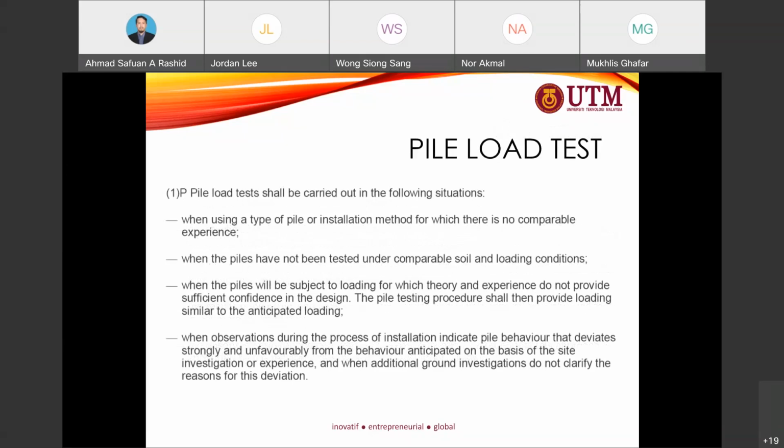So the pile test should be carried out when using a type of pile or installation method for which there is no comparable experience. When the pile has not been tested under comparable soil and loading condition.